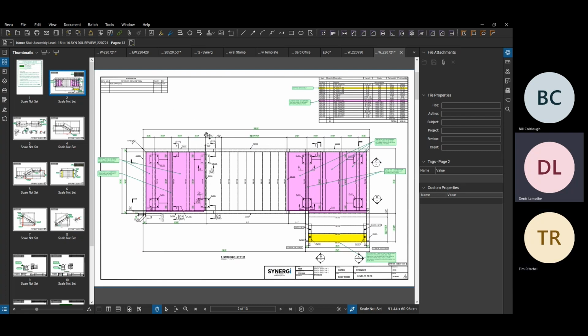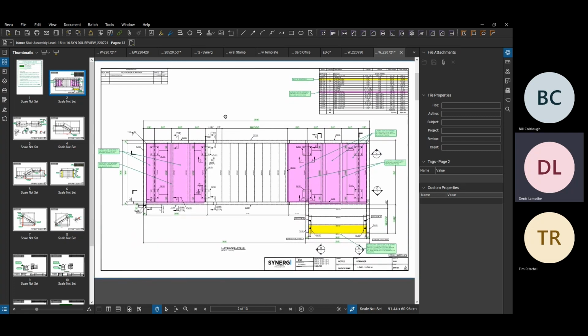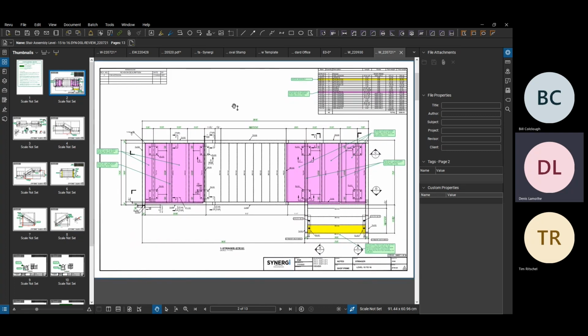And it could start looking a little messy when you're at the fifth floor and further up, and you really start having different panels. You might jump to panels 92, 93, 94, and then panel 4 because it matches similar panels on the first floor or something like that. So they may look at it and say, no, I prefer to have something a little bit more specific. So you can override it as needed. Okay.